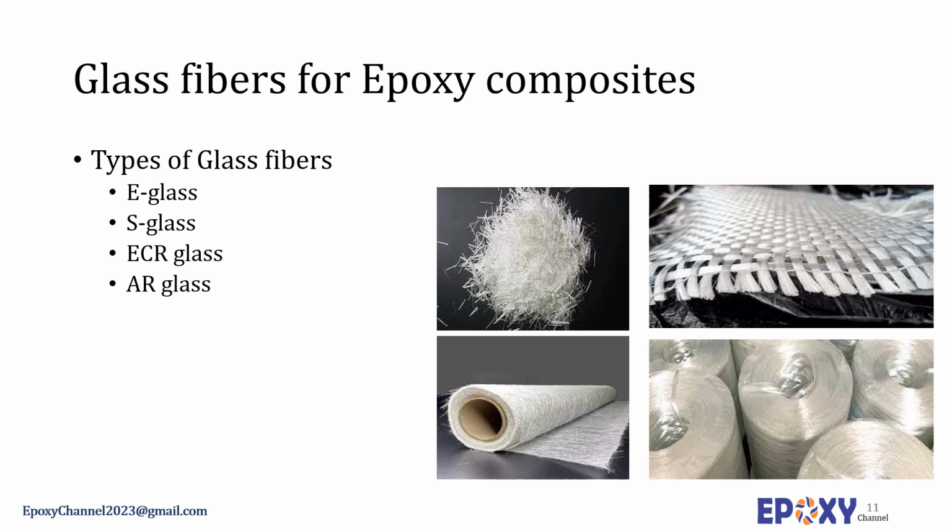The surface finish is a critical stage in the process, ensuring compatibility with the resin or matrix and high-speed conversion into composite materials. The finish consists of an adhesion promoter called a coupling agent, a protective polymeric coating or size binder, and other additives, for example, fatty acid, ester, or amide. It is applied in an aqueous medium, and for epoxy resin matrices, this will invariably be an emulsified epoxy resin.